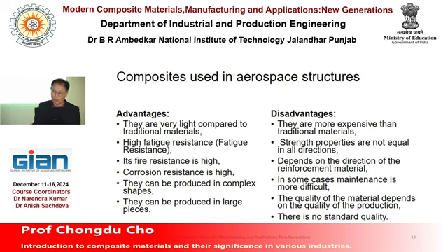After 2 million, 3 million, eventually 10 million cycles, it will finally fracture. But steel still has its limit. If it is a very low stress range, steel will not fracture at all. So differently from steel, aluminum has a great weakness in durability.